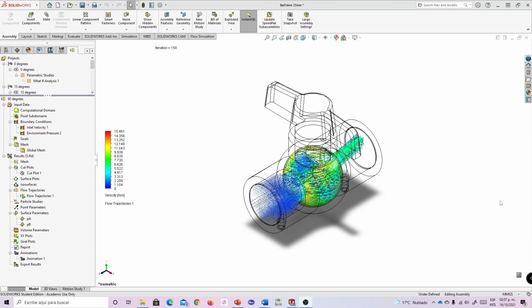What we are watching in this animation is a theoretically fully closed valve, and we could expect that this configuration will completely avoid the fluid flow, obviously, but some water is still flowing past this valve. This is because the diameter of the pipe and the diameter of the inner ball are slightly different.